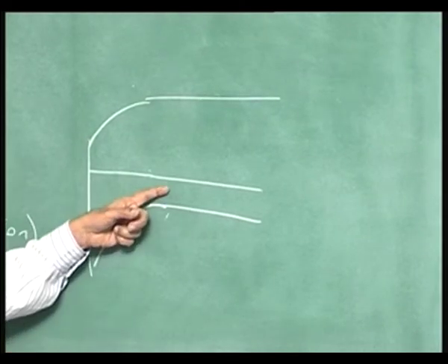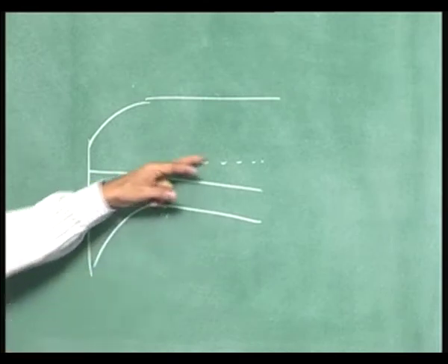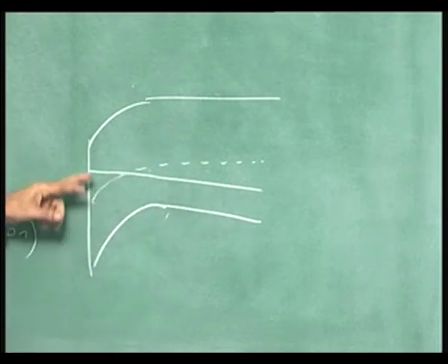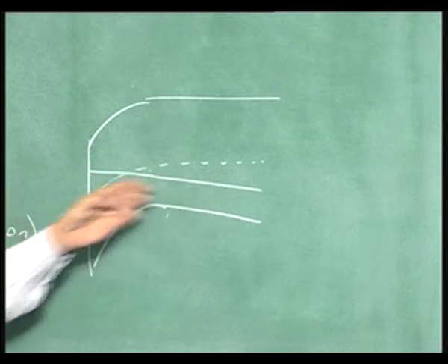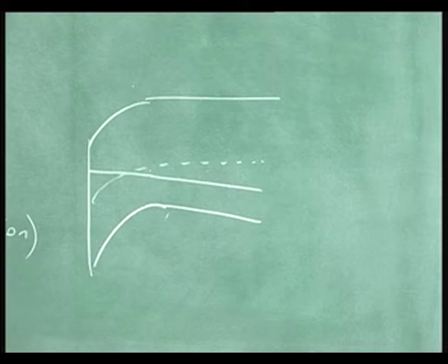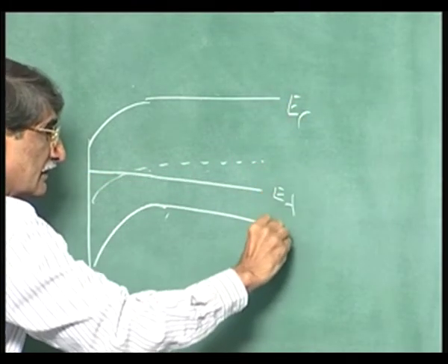This is the Fermi level and this is the intrinsic level. The more it bends down, the more it is towards n type, and more electrons will be there. In fact, if you move from here to here under thermal equilibrium conditions, you can plot the hole concentration and electron concentration. How will it be there? This is E c, E f and E v.